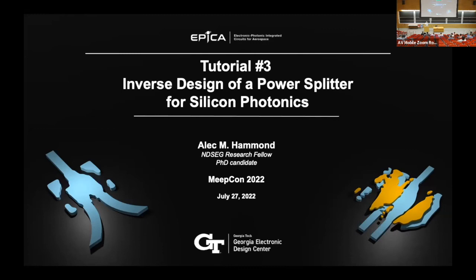I'm not sure I would put it that way, but the point is that whatever frequencies you specify, it's computing the DTFT at those frequencies and at those frequencies alone. There's spectral leakage that comes from truncating the simulation at too short a time, but that's independent of how many frequency points you select. Hopefully that answers your question, Ben.